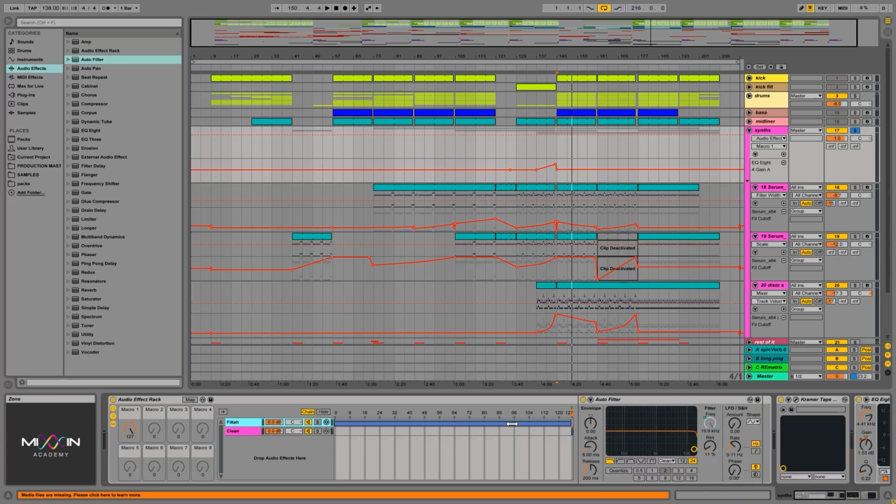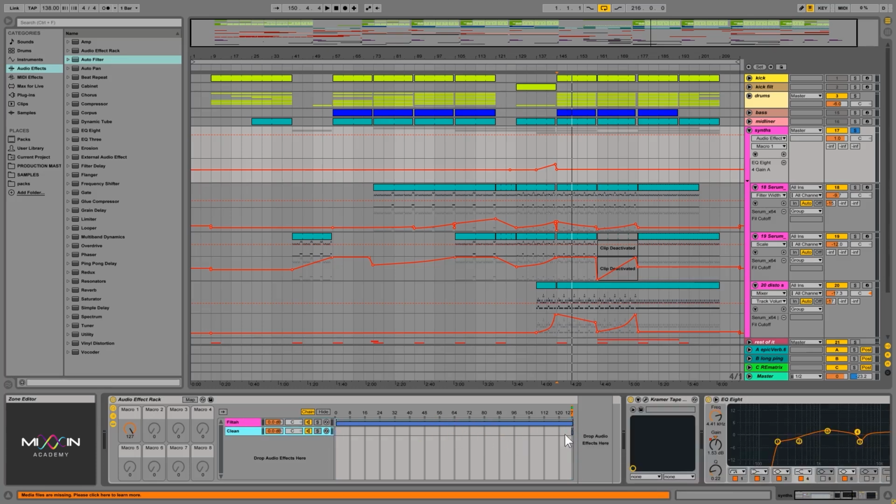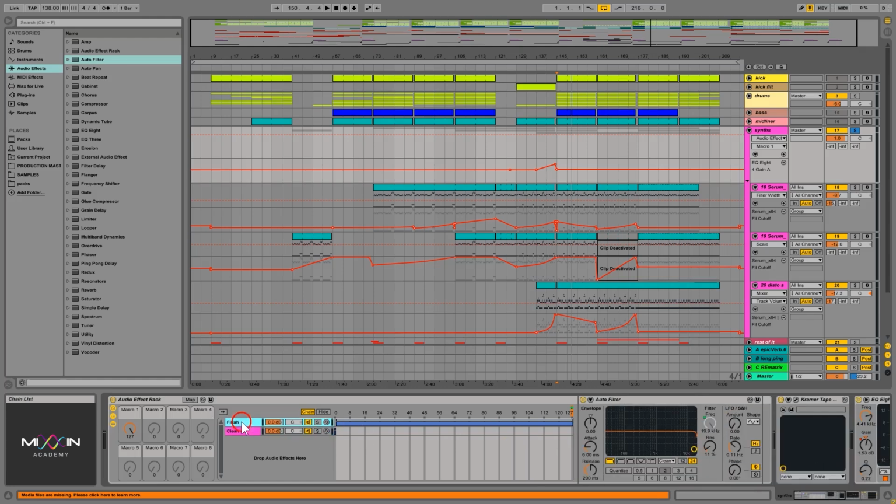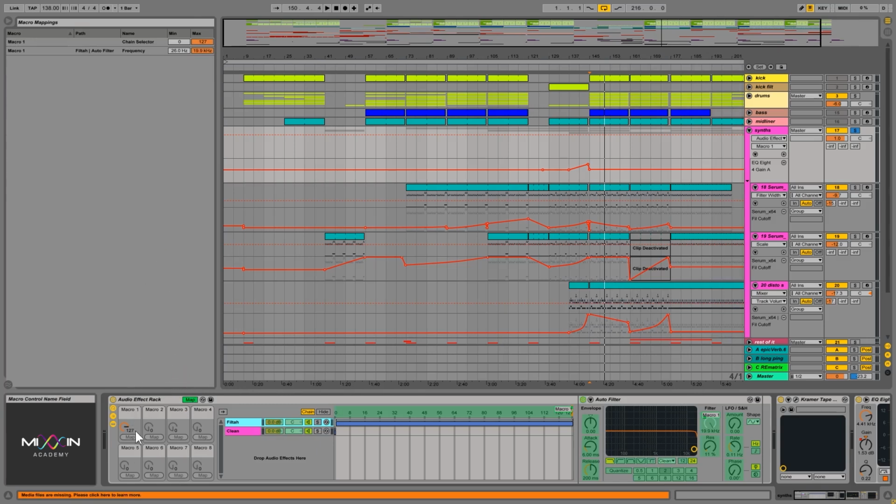And there's an easier solution to what we just did by moving this selection all the way up, all the way down. What I could have done to avoid moving this up and down is go to map, and you see this macro, I can choose it right here. I could have reversed this frequency selection.